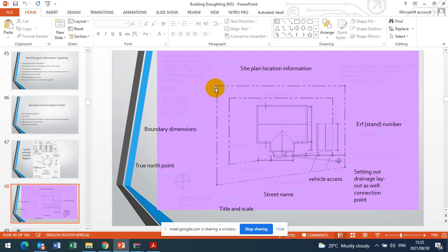Before you scale down, you must write your notes. Those circles are 600, 600, 600. Then you are going to offset the outside line, which is your property line, to get the building line. This is the building line. In many cases, the house will start on the building line. But I see this house did not touch the building line, only the garage. Can you see this is a garage? It is sitting on the building line, at least on one edge here.